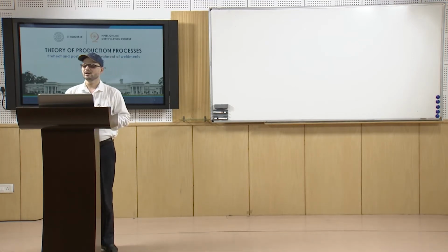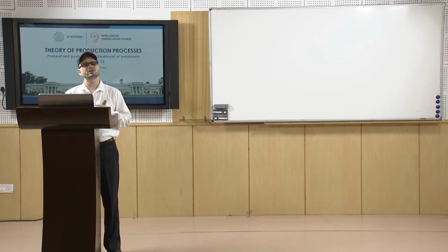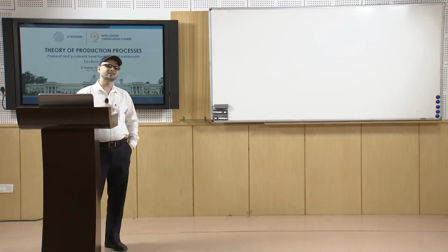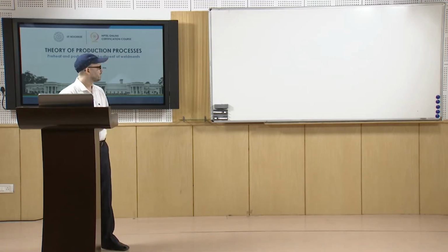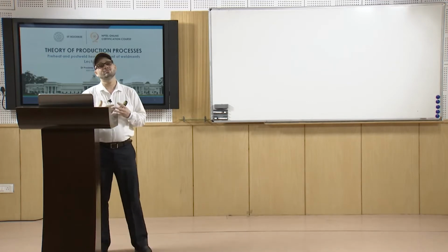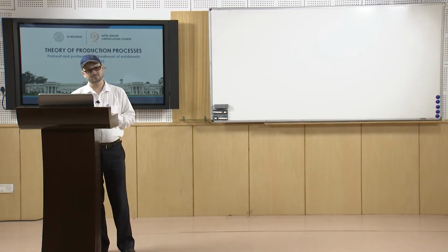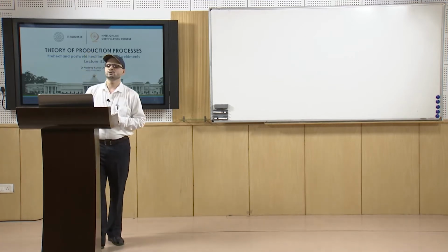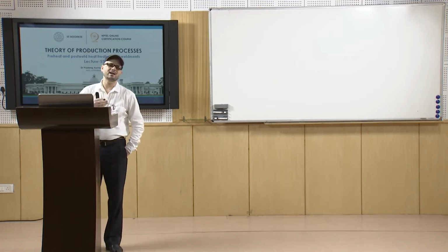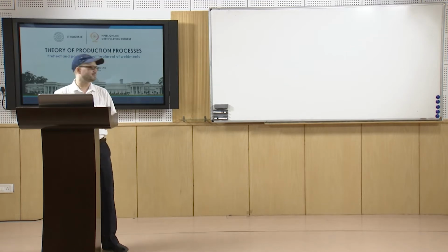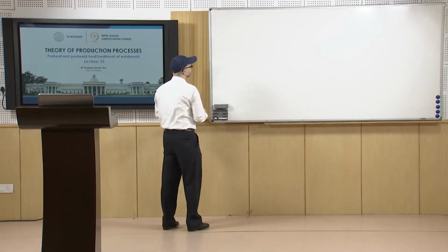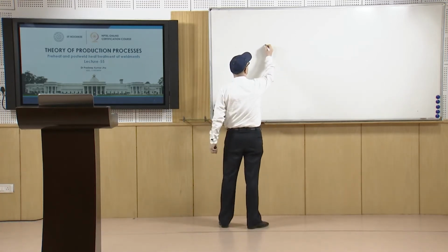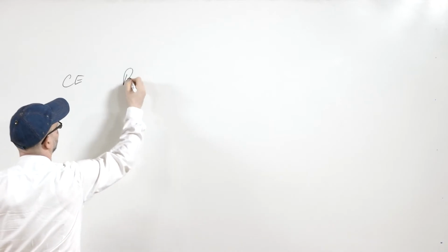So, it has been seen that if you are dealing with a plain or low alloy steel, and you have a carbon equivalent above about 0.4, then you go for a preheat of about 50 degree centigrade. Then if you have 0.45, it will go to 100. Like that, the carbon equivalent changes, and then the preheat temperature.